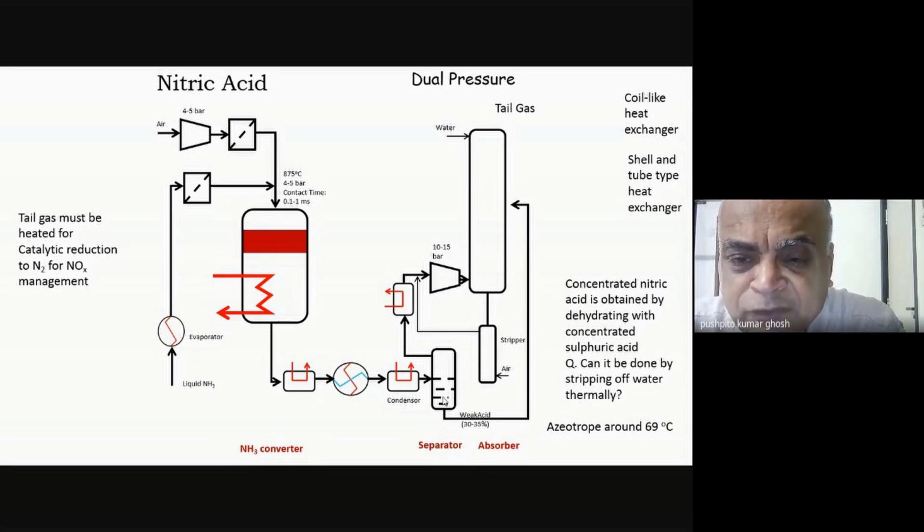So unless I have a sufficient concentration of oxygen, it will be difficult to convert all of the NO into NO2 in the second stage. So the air actually helps in that process, where you are effectively allowing the oxidation to take place, because you have injected more oxygen in. So that's what you're doing over here.